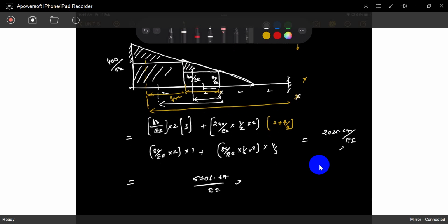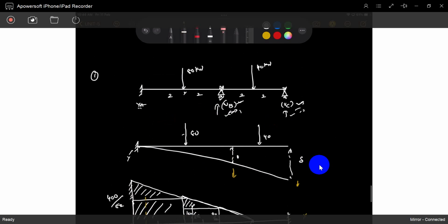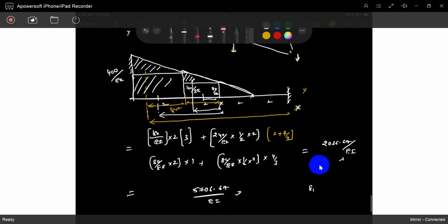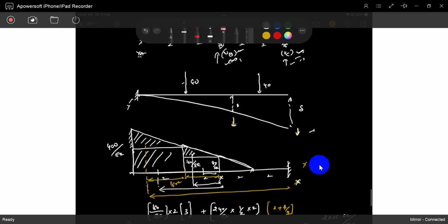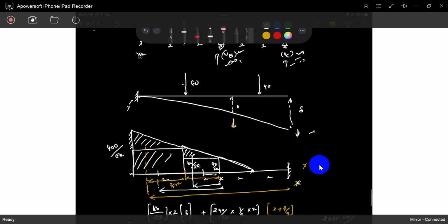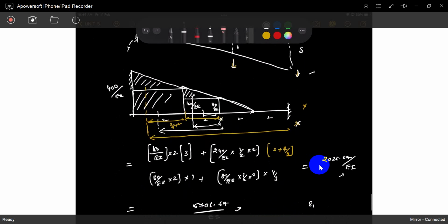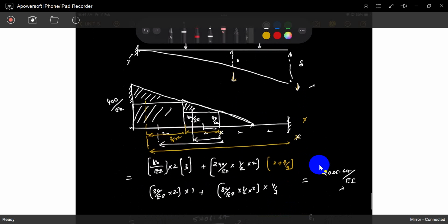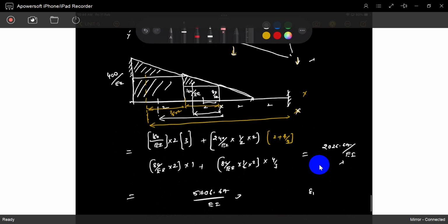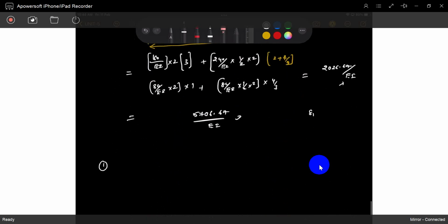So these are the deflections, which you have taken as downwards. These two are downwards. If you take downward as positive, these two are okay. If you take downward as negative, these two should be maintained negative. You should maintain that these two are negative. That is your choice. I don't compel you. Okay, so later, now you can find the flexibility matrix.